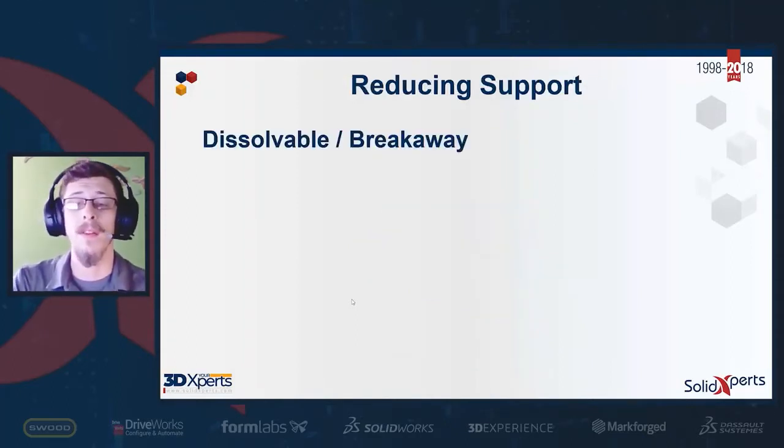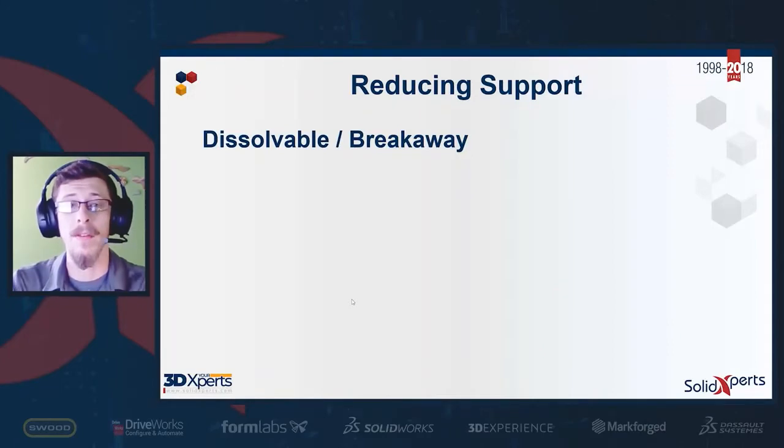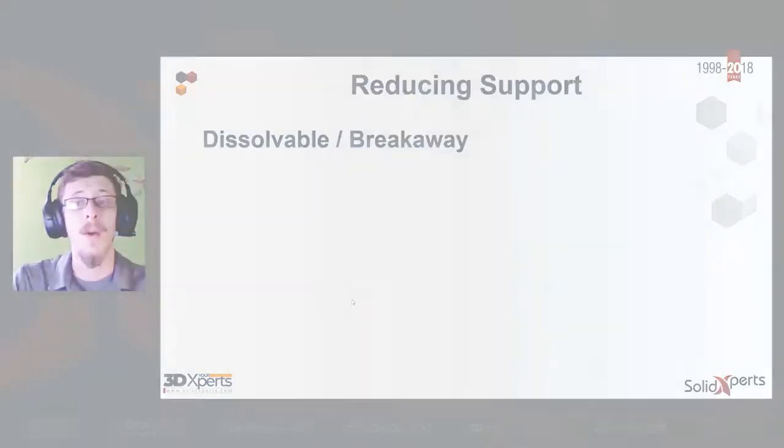Now, once we know what the support overhang angle is, and we also know what size nozzle we're working with, or the other sizes we may have, it's good then to discuss the support that we have and how we're going to use it. Now, there are two primary types of support. One being a soluble support. So this is made of a PVA or a filament that is either water soluble or it can be dissolved in a chemical bath. And a printer will use this as a support mechanism and use another filament such as PLA or ABS or PEEK as the primary material for the part.